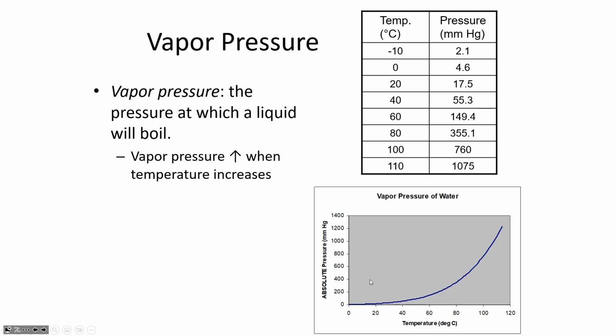Pressure was lower, right? So high velocity, low pressure. Low velocity, higher pressure. If Dr. Yoon had really let you crank that thing, like really just put lots and lots of water through that venturi, what you'd find is that there's a certain velocity that's so high that it causes a really low pressure of the water. And in fact, if the pressure in the throat of a venturi gets low enough, then you can start to see little vapor bubbles form.